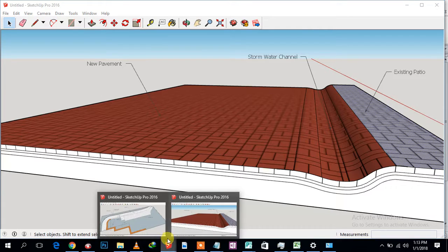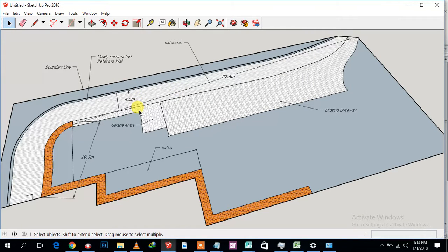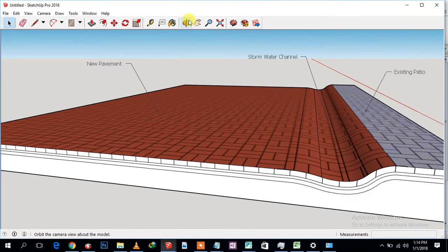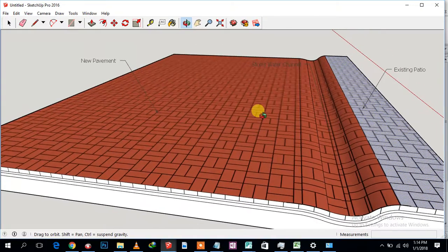And here in front of the garage, where we're going to build a new garage, we could do it now, or we could do it later when the garage is about to be built. We could lay a drain channel. We then top it with those galvanized grates that are already at the house that we used for steps. We top them on top, and then it's going to be in front of this pavement. I will explain further when on site.